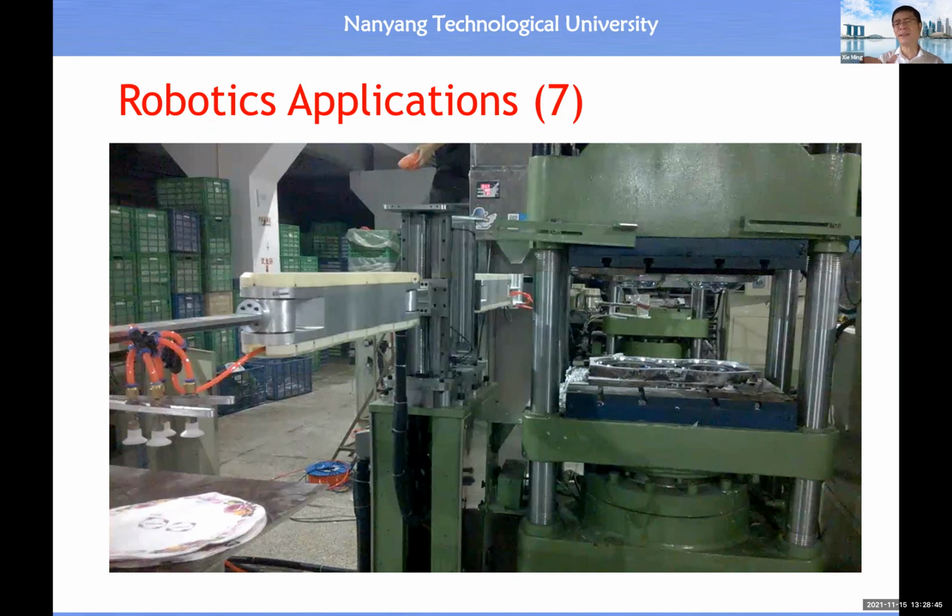The sintering process will take powder as an input, then produce a solid as an output, and the solid object will take up the shape of the inner cavity of the die. The die has an upper die and a lower die put together. Then inside we have the geometry of the cavity. So the output solid will take up the geometry of the cavity of the die.